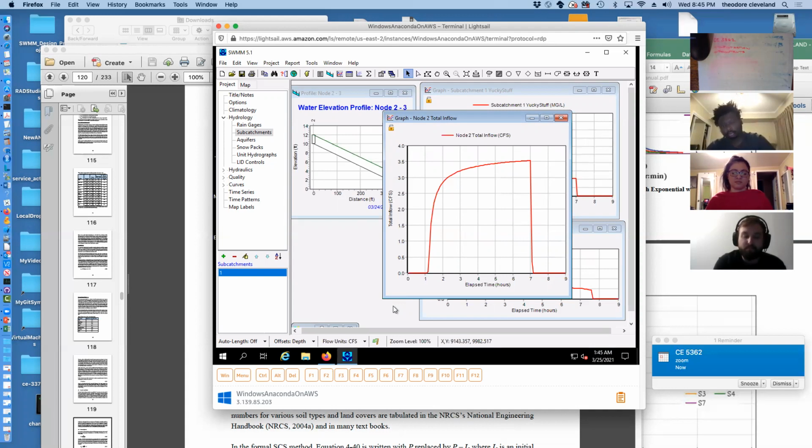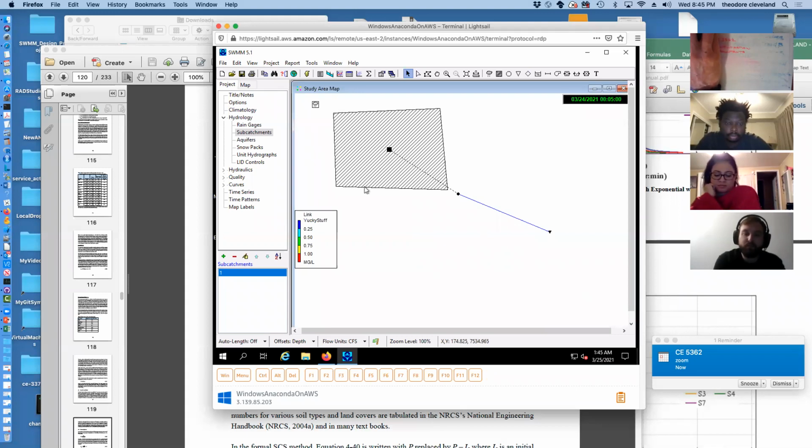So if you're working for a client and they're arguing that your Horton's method is BS, switch to Green-Ampt. You may have to jack around a little bit to recover your Horton parameters, and odds are the numerical values you use will be defendable from the literature. So at this point, as far as the per subcatchment hydrology is concerned, we've now explored the two ways of generating runoff.